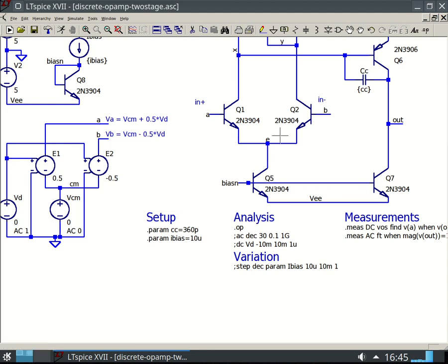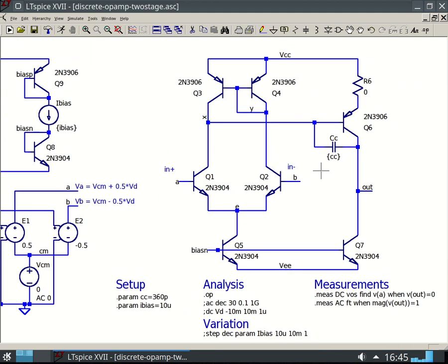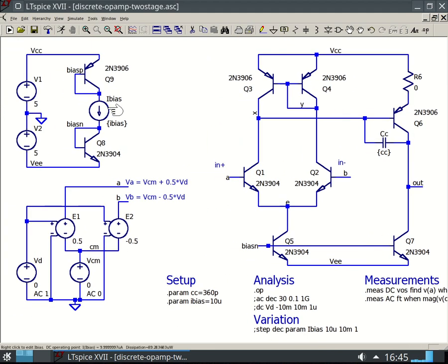Doesn't matter for us. Okay, so what we can do in LTspice is hover over this, and you can see in the very bottom corner it says right click to edit iBias. You might have to zoom in or something. And it says iBias is 9.99999 whatever 7 microamps. Well, of course it is, because I said iBias was 10 microamps.